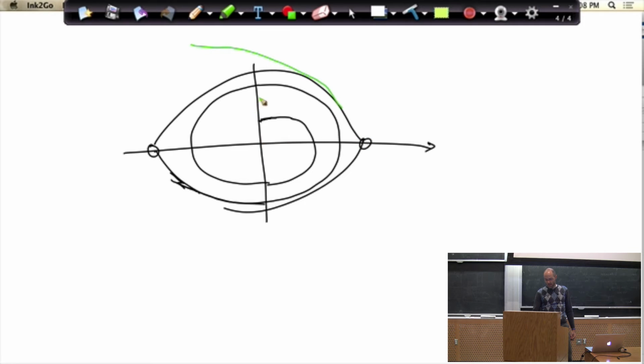Okay, so certainly if we were to do the energy shaping where the desired energy was 0, we'd get something here that would do exactly the right thing and would stabilize the origin. If we did sort of change coordinates there, then you'd like to get something like this. But if we have saturations or something like that, that would get us closer to the feedback linearization idea. And we didn't actually need feedback linearization to write this controller, right? So if we just look at this controller stabilizing now this non-zero energy, then it's a little different than a coordinate transform from here to here. It's a potentially gentler controller that could get us there, right? I could just be pushing a little bit of energy in all the time and slowly get myself up without ever overriding it. So it might be a little better.